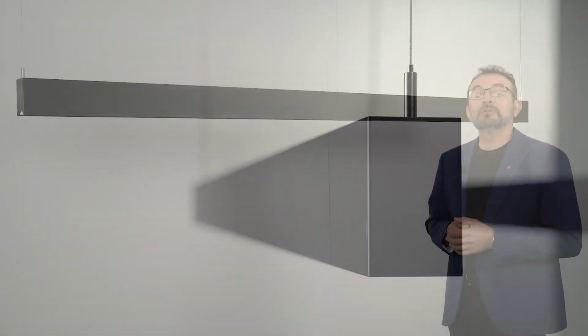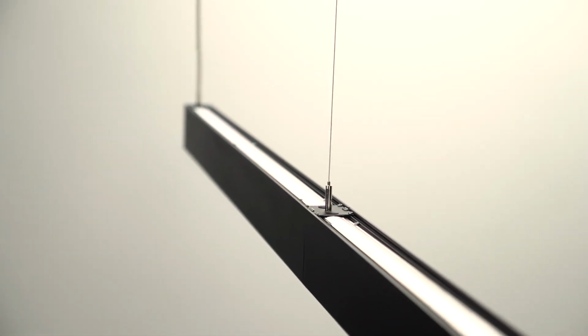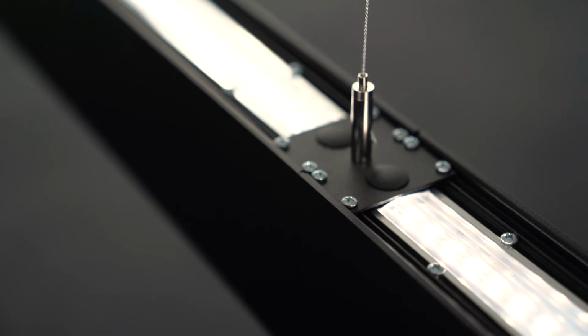The mounting cables are available for both hard ceilings and T-bar ceilings, with standard lengths of 3, 6, and 9 feet. All of our standard fixtures use only 2 suspension cables, one at each end, including the 12-feet fixture, unlike other brands that might require cables every 4 to 6 feet. For the continuous run, you'll have 2 cables at each end and one at the joint. It allows you to have the cable spaced at 12 feet distance with much cleaner look.